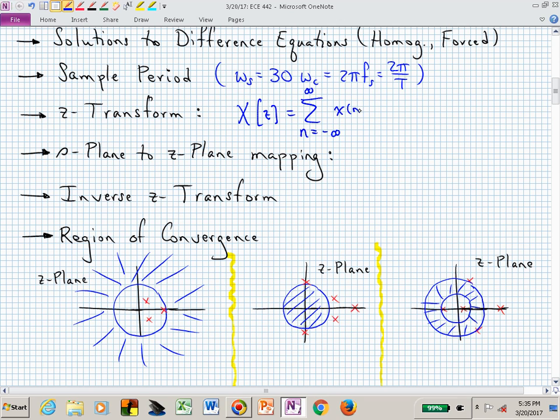And we now weight that time sequence of values, little x of n, by this complex variable raised to the minus n power. And z to the minus 1 is like a delay. And now we are weighting these time domain sequence values, little x of n, by delays in a sense, and that now produces this Z transform.